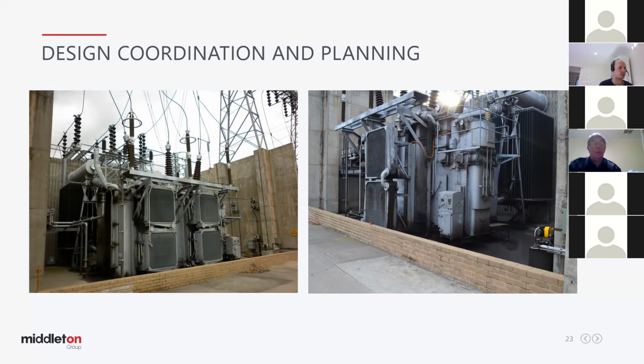So that's general primary considerations. CTs, how many neutral CTs are required? Are they external? Are the current transformers within the bushings of the main transformer? How are cables going to come from those, et cetera. So we need to look at the plant, identify where things will run from, where they're situated, and then interface with the primary team to then effectively make it happen.